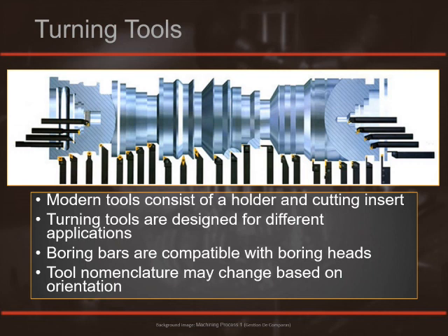Shown, there are several types of tools: a threading tool, outside profile tools, inside profile tools, grooving tools, and parting tools, as well as boring bars. It's important to plan your tooling needs as you evaluate a drawing before you start programming.